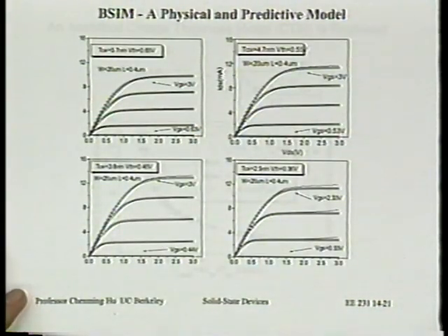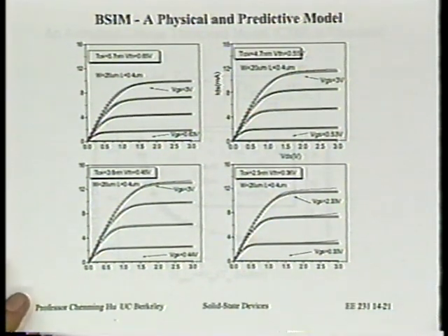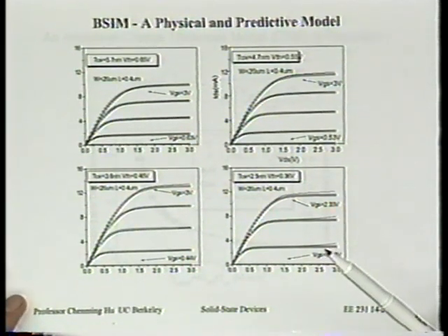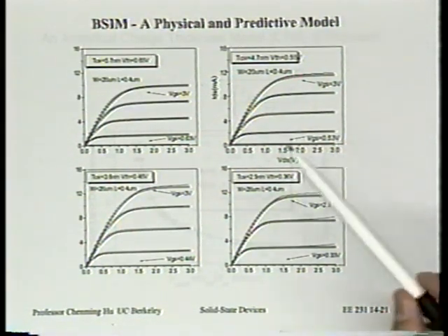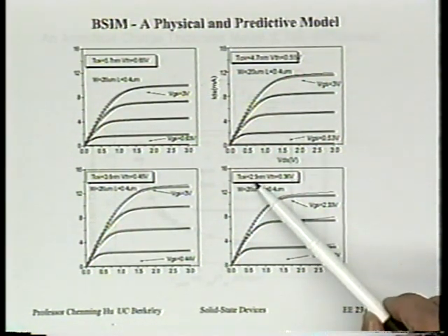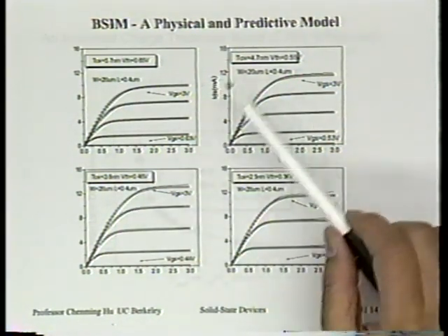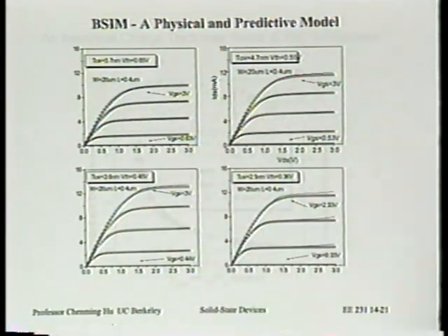Okay? And here's an interesting plot. This turns out was data given to us by AMD. Earlier I showed you some transistors made by students themselves. Now here is some data from the industry. This is experimental devices where the engineer just asked the fab to change the oxide thickness between 2.5 nanometer, 3.6 nanometer, 4.7 nanometer, and 5.7 nanometer.